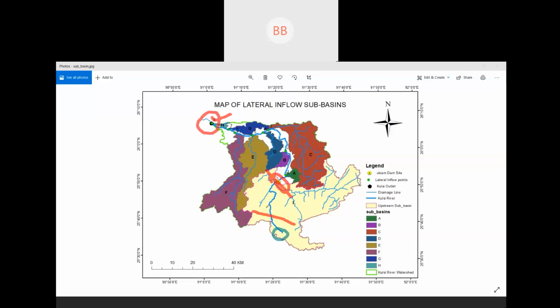It depends on you, you take here or here, doesn't matter. Then you take the RL of this portion where you require to find the slope. Then you use tan theta, which gives you the slope, so you will get the appropriate one, not the exact one.